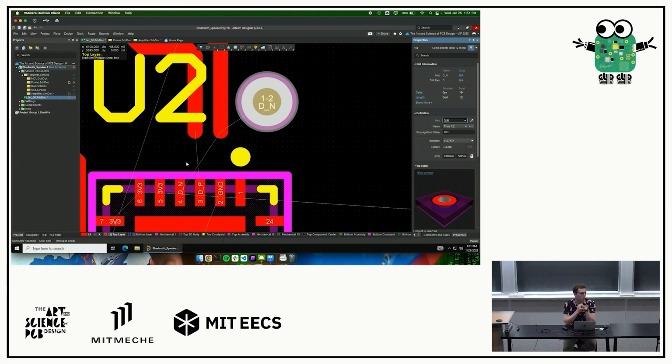Just in general, you usually want to minimize them. Back in the olden days, it used to cost money to put a via on the board. That has generally since passed. But when we put a via on there, that's a hole that goes through the whole board, right? And so if we wanted to route a connection on the bottom side of the board, we couldn't in that same space, because there's a via occupying that section of the board. So generally, you want to keep them a little bit sparse for that reason, so it's just easier to route. And depending on how you do some things with your ground planes, it can also cause some weird signal problems. But generally, we'll say it's convenience for now. Yeah.